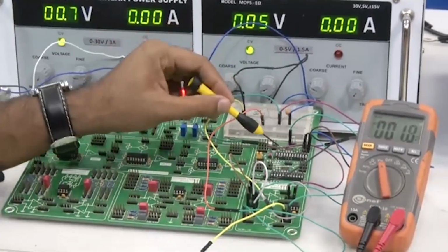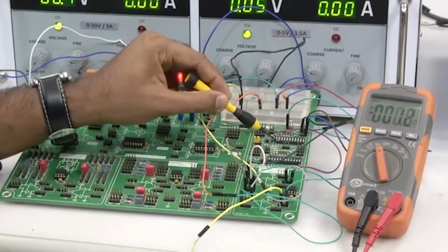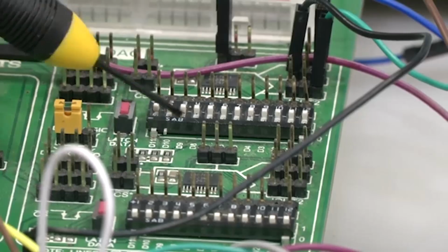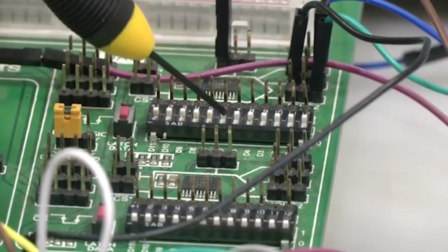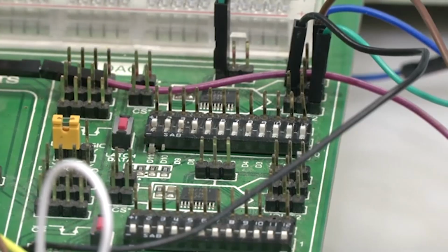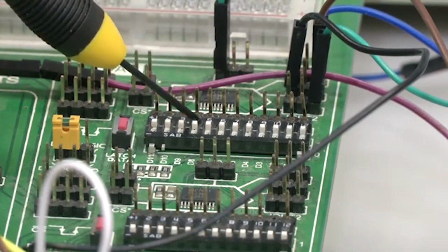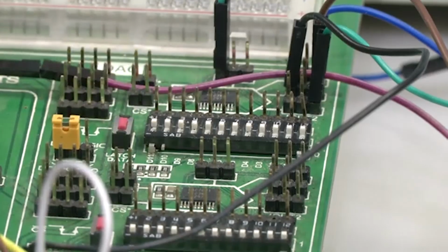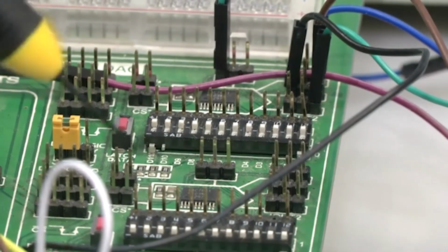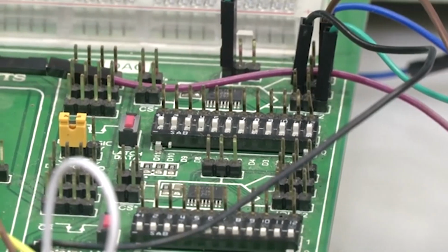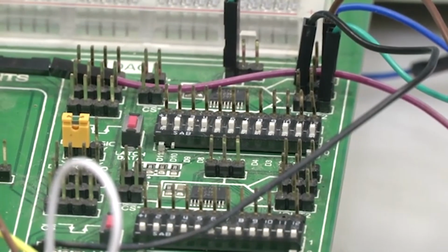Now, let us just focus once on the bit sequences. Yes, now we can see the bit sequences. If you can see, now all the bits have been pushed up like this. Now, we will only focus on the multimeter after this. You will not be seeing it, but I will be changing a few bits, and we will accordingly see in the multimeter how the voltage is changing. Now, let us see what the voltage is when all the bits in the DAC are high. So, let us focus on the multimeter.